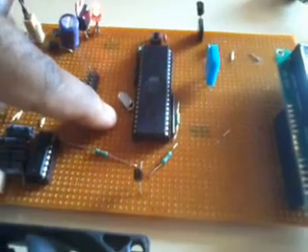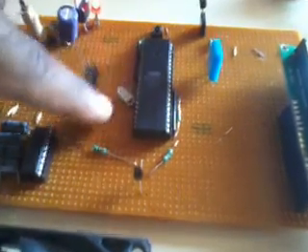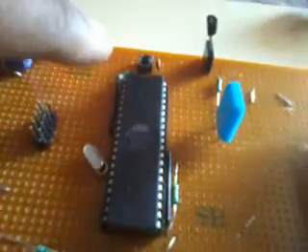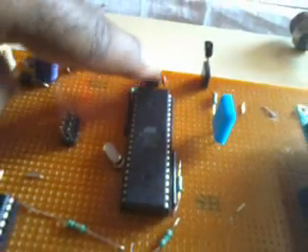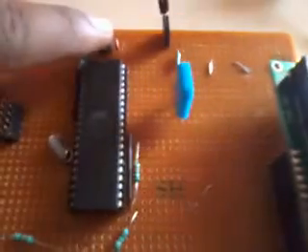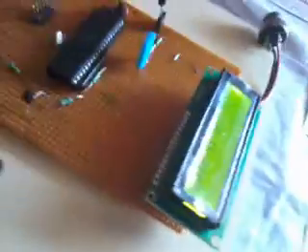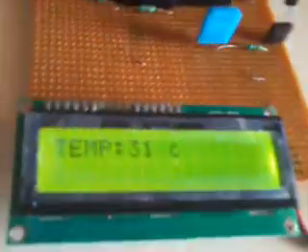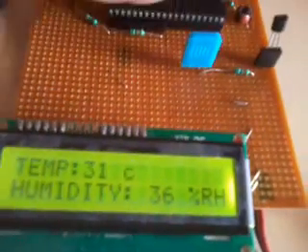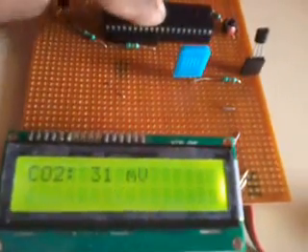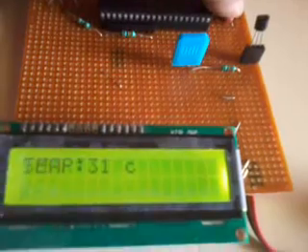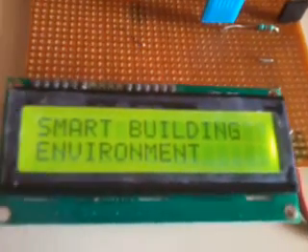Here I used a 16 megahertz crystal. This is the heart of the circuit for the controller to run the internal program. Here I used one switch, called the reset switch. When the program is stuck, we need to restart with it. Port C is connected to the 16x2 LCD display, a character LCD display. Whatever process is going on in the controller should be displayed on the LCD.